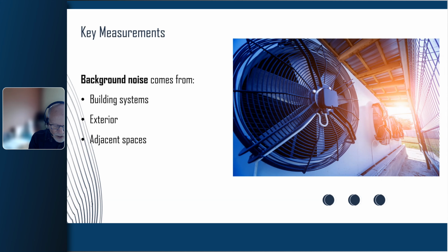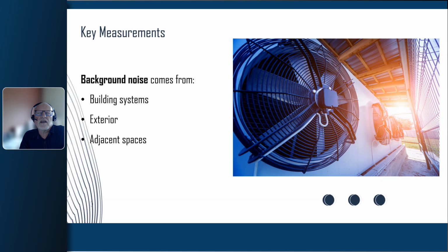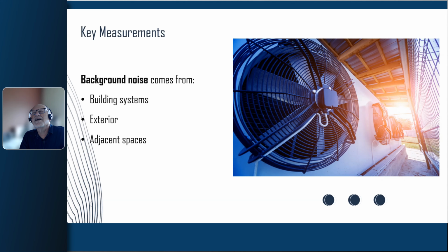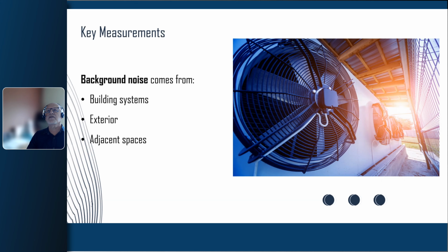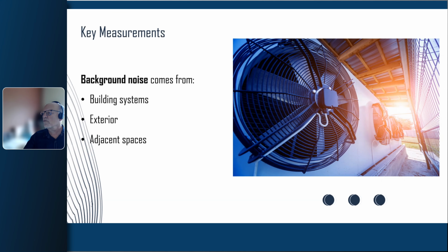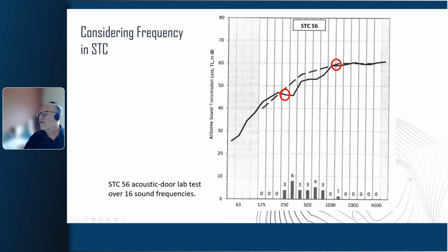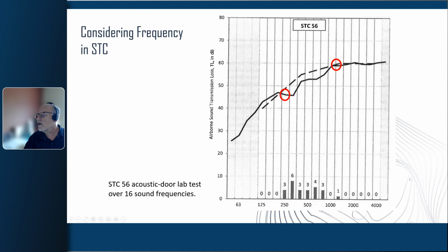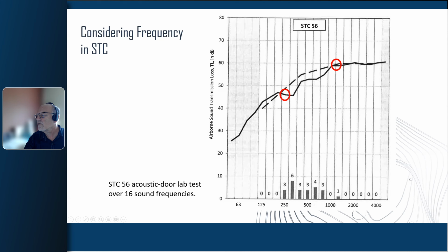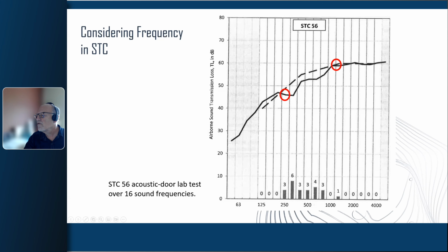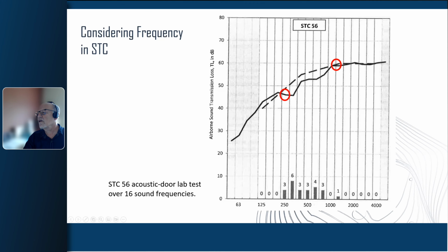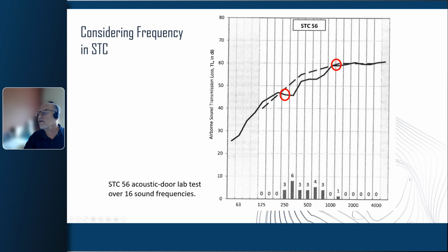Okay. Again, good question and really right. It's like a planted question. You've got low frequency noise, and you're probably going to want an STC 50 as a minimum, because as I showed you back on this, your HVAC systems are probably running in this area of 250 to 500 hertz. So you've got between 48 and 50 decibels of noise there. So that's pretty good if you can achieve that with your STC 50.